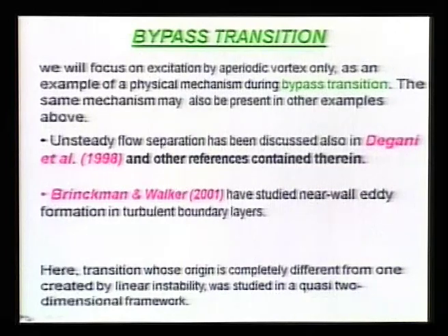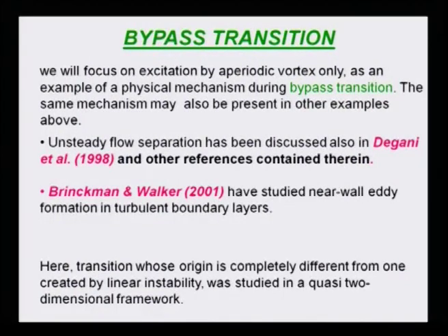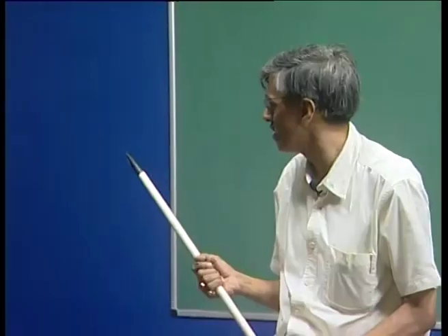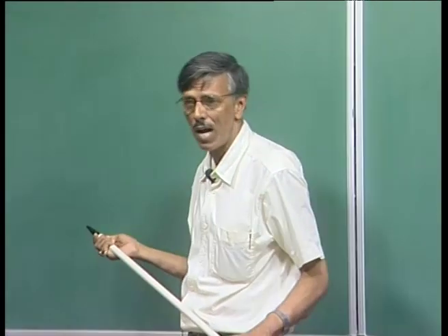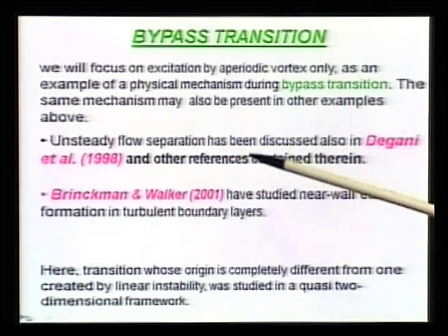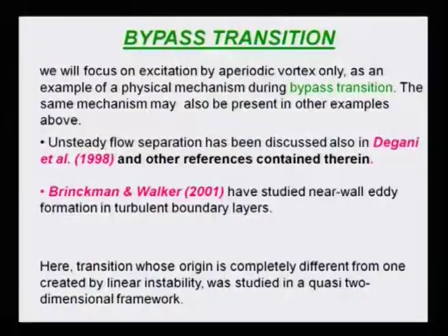And these are the potential application areas where you see such a thing happening. For example, we have talked about, in fluid mechanics, unsteady flow separation. This is a paper, Degani et al. They wrote about it. This unsteady flow separation implies that you would have separation bubbles which will go along the surface. And they also show you enhanced skin friction and significant separation. Separation phenomena, we will club them as bypass transition.